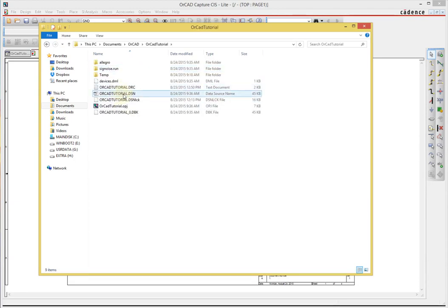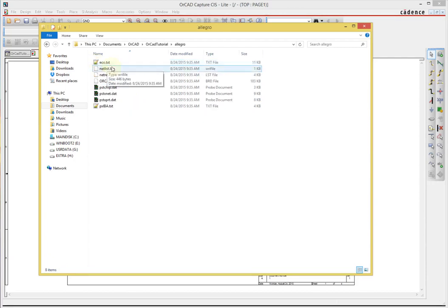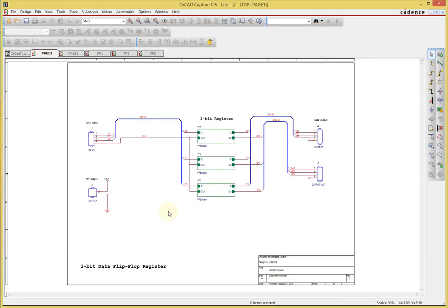and we have our design file, which is part of our specific design, and then there's the OrCAD project file. So your design file is actually contained inside of an OrCAD project file. So everything goes together. And then Allegro is the folder that was created specifically for the PCB. If we double click on it, here's the information, but our key file is this file right there. That is the board file that we're going to use to begin phase 2, which is the layout phase of our existing schematic design. And we're going to cover that in a second video.